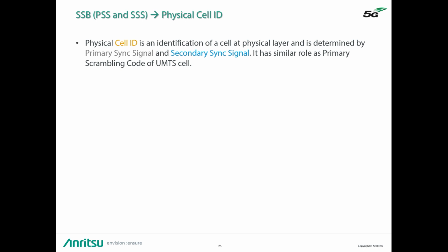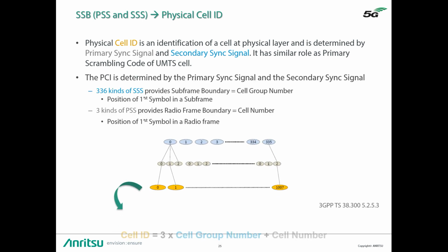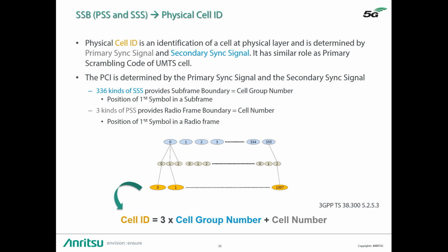The new radio cell search is based on the primary and secondary synchronization signals, PSS and SSS, and the PBCH-DMRS, which is located in the synchronization raster we've already spoken about. Once the PSS and SSS are known, it becomes easy to calculate the cell ID, as shown here with a formula.